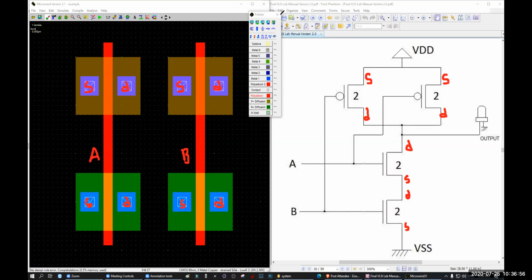Now I'm going to choose, oh, by the way, see, since source and source are connected, this source and this source should be connected, and drain connected, so this drain and this drain should be what? Connected, right? The source connected and the drain connected, right? For PMOS. Understood?